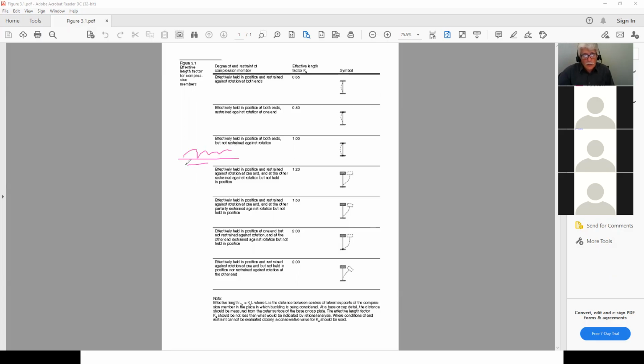It's going to transfer there, then there, and then here. So these are load paths. You have to always think of how the load is going to go through your structure and what the elements are that are going to eventually resist what you need to resist, understand? And ultimately it's your foundations that are going to resist so that the whole thing doesn't sink on you. That's why you have to design these accordingly.